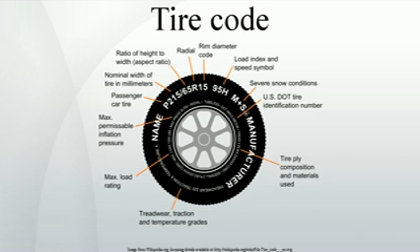For Euro-metric tires, the term reinforced means the same thing as extra load. Arrows: some tread designs are directional, and designed to perform better when driven in a specific direction, clockwise or counterclockwise. Such tires will have an arrow showing which way the tire should rotate when the vehicle is moving forwards. It is important not to put a clockwise tire on the left-hand side of the car or a counterclockwise tire on the right side.